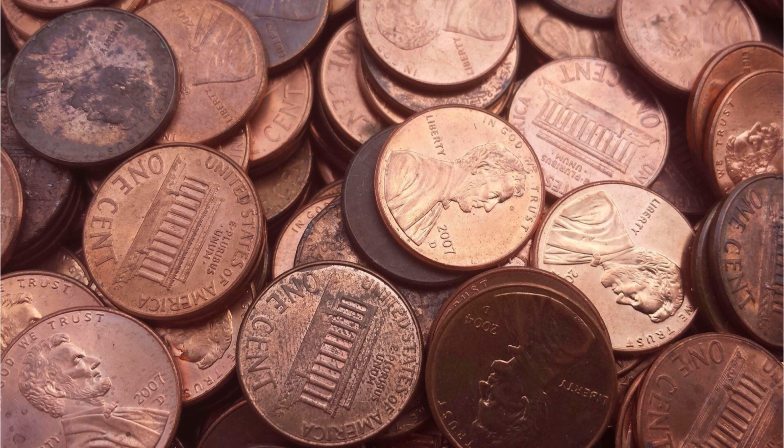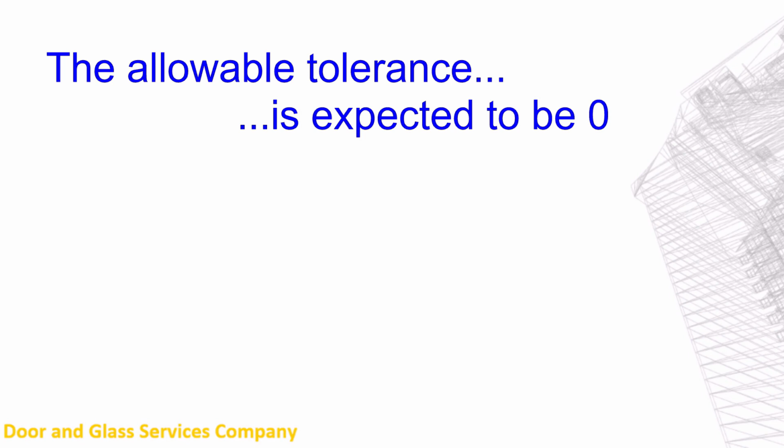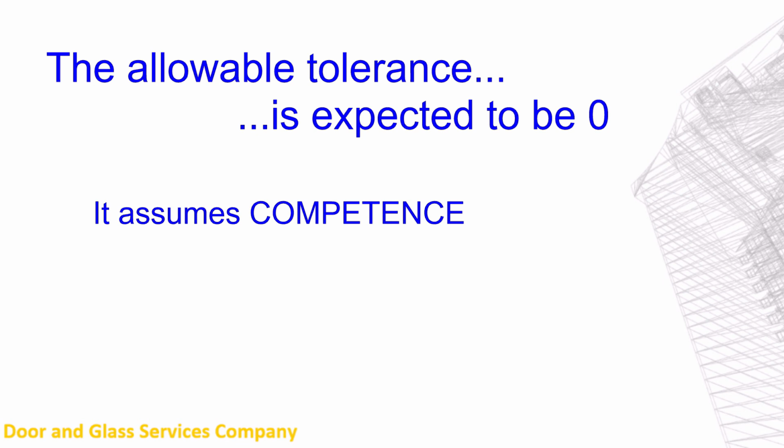In a perfect world, there is an equal chance that all errors will be more or less than the expected dimension. Perhaps an operator believes it's okay to locate a clamp once and proceed to cut 100 pieces of material the same size, and they don't check any of the cut dimensions.